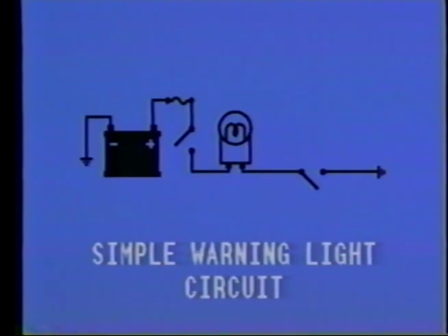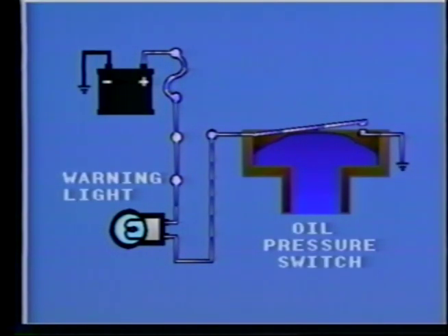Performing a mechanical oil pressure test will steer us in the correct direction, but if we have an understanding of how measuring circuits work, diagnosis may be made simpler. Warning lights or buzzers are typically simple circuits receiving current when the key is in the on position and grounded by some sort of switch. In the case of the oil light, a pressure switch is located at the engine block, which causes internal contacts to close when there's low oil pressure, thus completing the circuit ground.